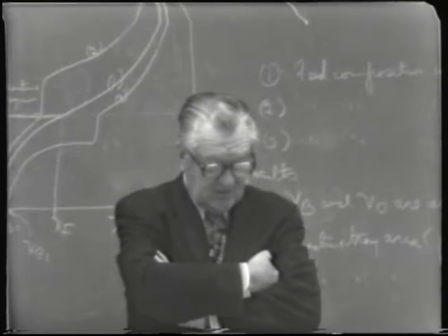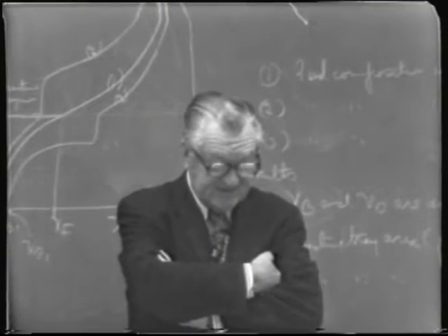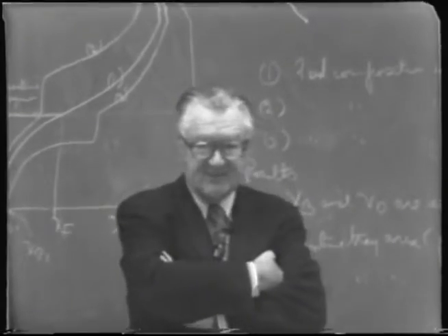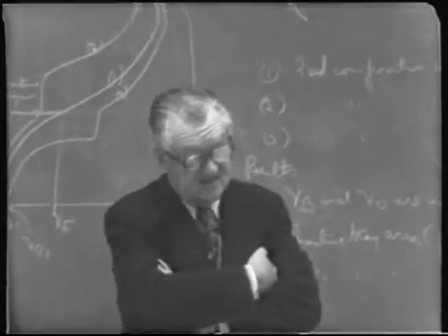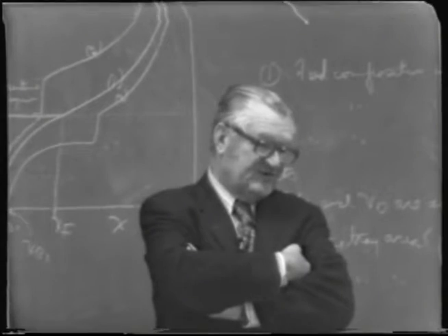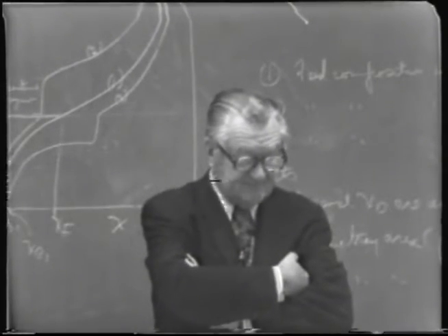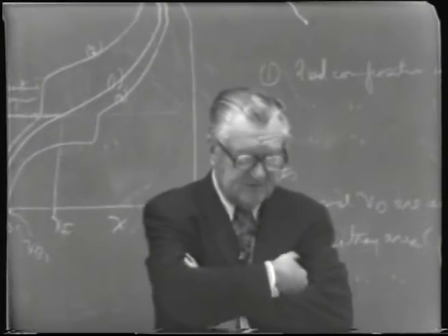To get allowable loss of the order of 0.02% alcohol by volume is about the limit that can be attained with any of our equipment. 0.05 is probably more typical of the concentration of alcohol in the bottoms.